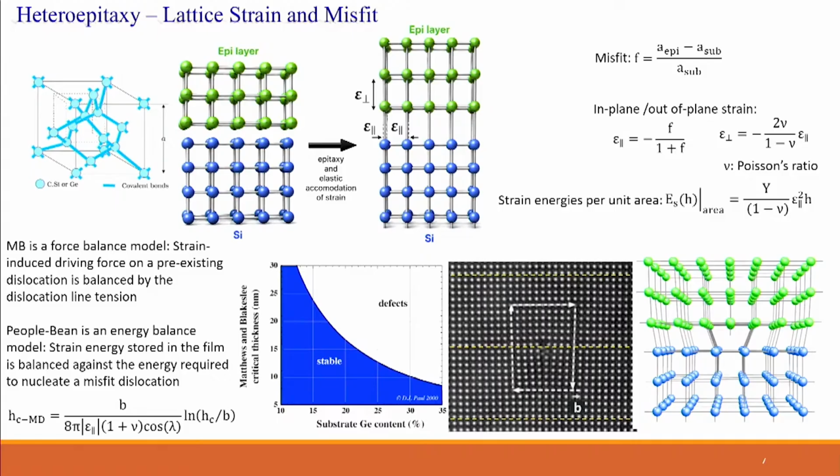It's a crystallographic parameter, so you start by drawing a contour that surrounds the dislocation. Let's say you start from here. You go 1, 2, 3, 4 steps to the right, 1, 2, 3, 4 down, you come back 4, then you go up 4. You see that because now you have a dislocation, you are no longer able to close this loop. So this extra crystallographic vector that you need to close this contour is what is called the Burgers vector.